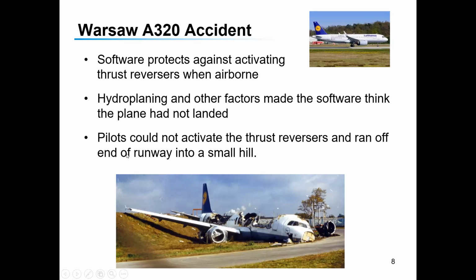Now, when it's landing, the software is supposed to allow the thrust reversers to be activated, but there was a lot of water on the runway, and there was hydroplaning and other factors that made the software think that the plane had not landed.